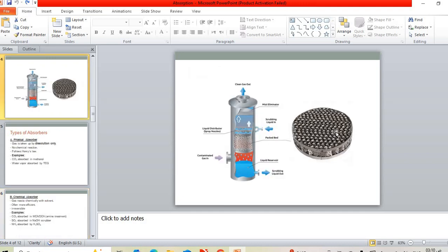And this is another, more detailed diagram of how it looks. So we have a bed over here. You have the contaminant gas at the bottom. And of course the gas enters from the bottom because it has low density. And here a solvent goes from the top, and both meet here in contact to spend some residence time and increase the surface area of contact between both phases.